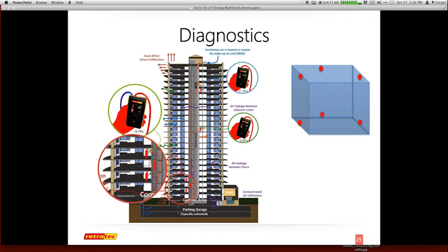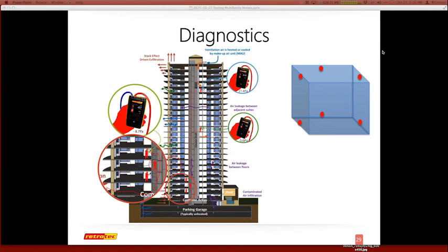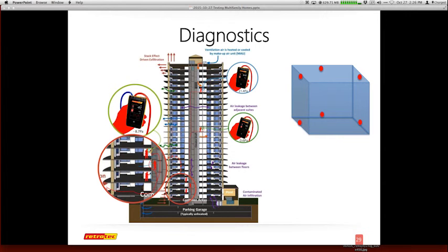So here's a diagram that I made. Again, this is definitely a high-rise type of structure, but this is also multifamily in general. One of the things you can be doing is confirming whether or not you have connections from your unit to the hallway. One of the things that happens in these units is their ventilation system. Right now, though this will be changing soon, you have a ventilation system running down the entire path. You may have two or three depending on how tall the structure is, and they're trying to keep all the bathrooms at a slight negative pressure all the time, 24/7, because most people no longer have their own individual fan or even a booster. That's a major impact throughout the entire structure, and it can be a significant, measurable number.